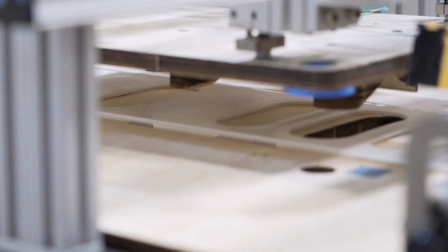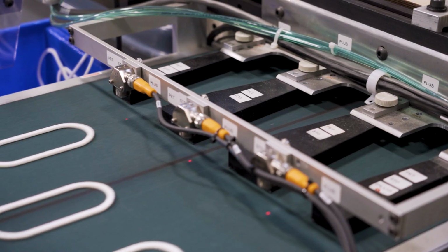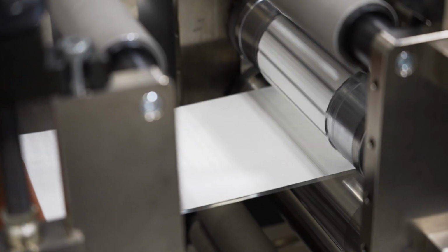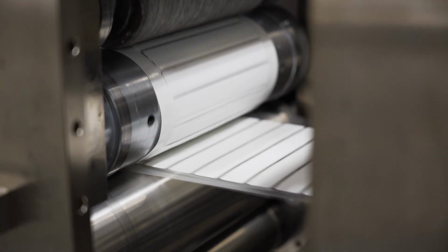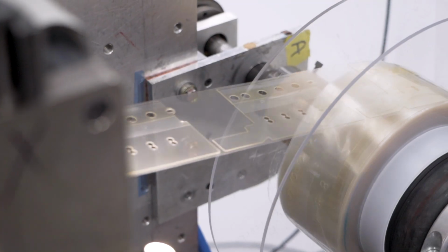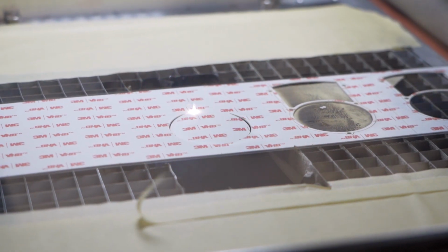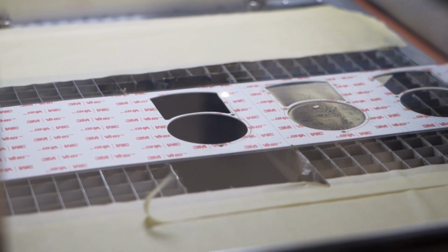Depending on the material or project requirements, manufacturers might use a flatbed cutting process if the parts need to be sheeted or if the material is thicker and harder to deal with. On the other hand, rotary die cutting might be preferred if you need parts in a higher quantity or you want them to be finished kiss cut or onto a rolled liner. And lastly, you can use laser cutting as a non-traditional tool-free alternative to achieve similar results.